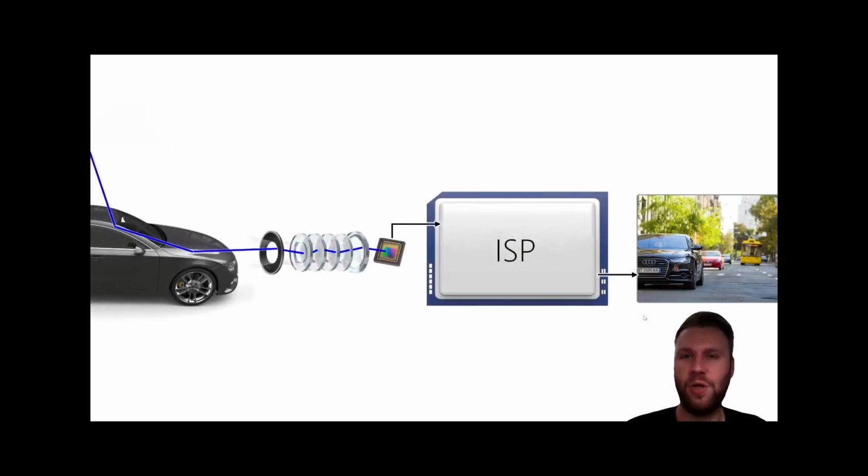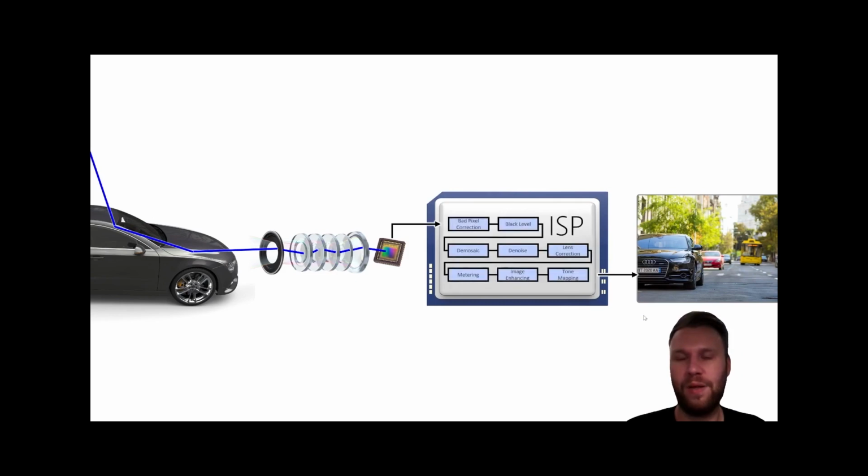Existing conventional camera systems have in common that they're relatively compartmentalized systems, with light coming from a scene being focused by a set of refractive lenses on a flat sensor surface, where that light gets digitized, and the digitized image that we read out from such a sensor is then processed by an image processing pipeline, the ISP, which can output, after a set of fairly involved image processing operations, an image that we can display and show to a user.